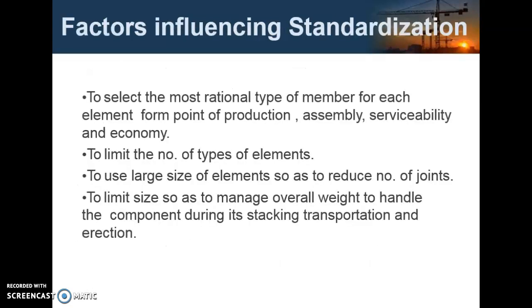Factors influencing the standardization. The main purpose of standardization is to limit the number of types of elements and the number of sizes of elements, to use large sizes of elements so as to reduce the number of joints, and to limit the size so as to manage the overall weight to handle the component during its stacking, transportation and erection.